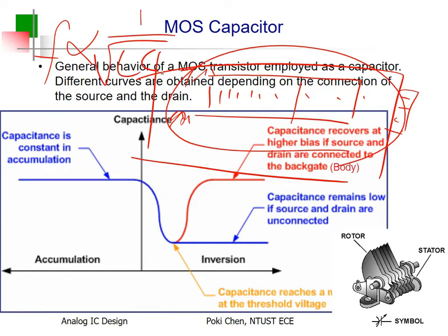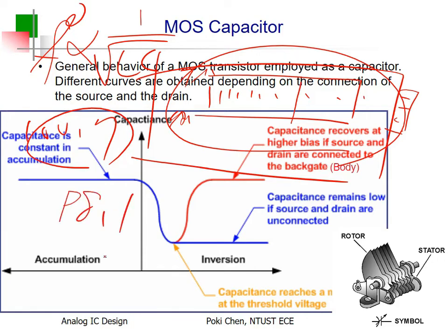In brief, for such kind of analog radio, the frequency is reversely proportional to the square root of LC. Yeah, how to tune the frequency? ICRT, 100.7, right? And some kind of a classic radio 98.1, blah, blah, blah, blah. How to change the frequency? You can change either inductance or capacitance. But to change inductance, I think is much, much harder. So usually we change the capacitance.